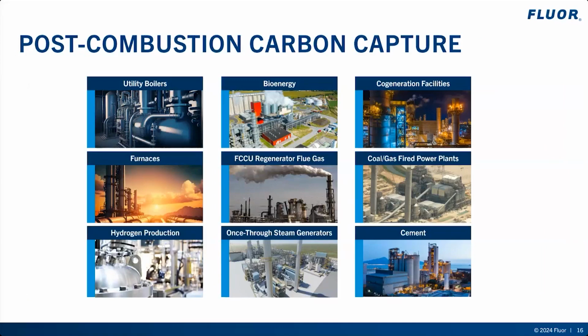In connecting with some of the challenges highlighted on the previous slide, they are effective in recovering CO2 from flue gas sources with low concentrations of CO2, including power and cogeneration applications. For flue gas sources with high concentrations of oxygen, a properly designed system can appropriately mitigate reduced system performance associated with the oxidative degradation in an oxygen-rich environment.